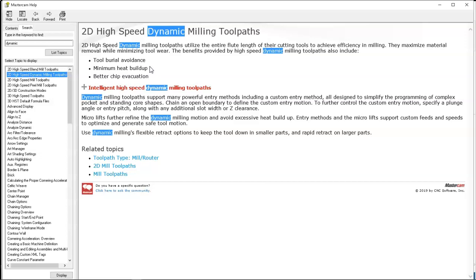And so I've gone over to the cold air gun or machining dry, and as long as I adjust, I'm not losing much time for the rigidity of the machine, but I'm not having to do all the cleanup and deal with the nasty. So one of the things I'm really concerned with is evacuating that chip and having it carry as much of the heat as possible.